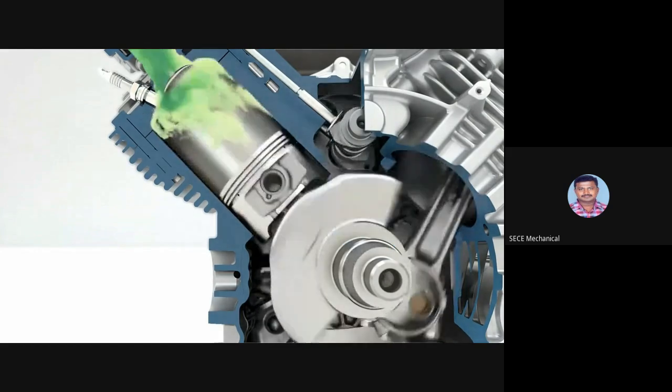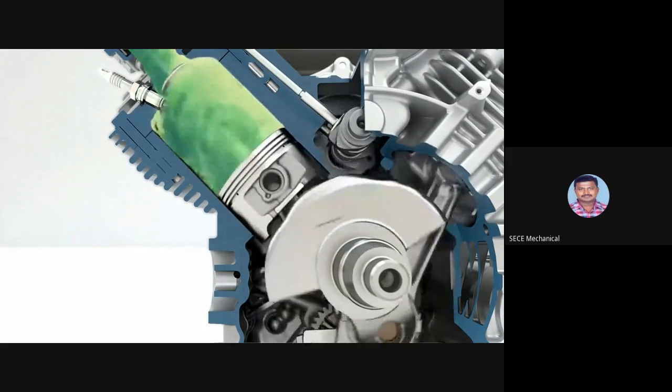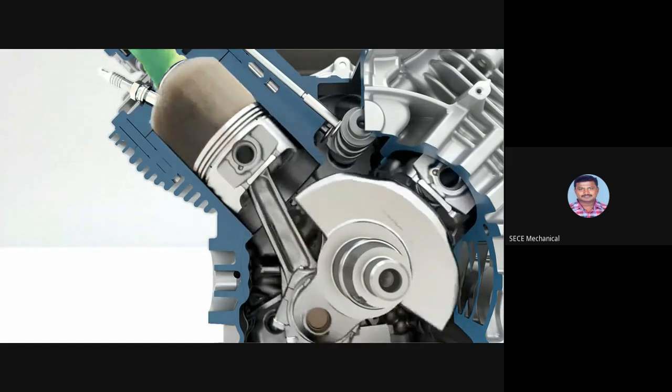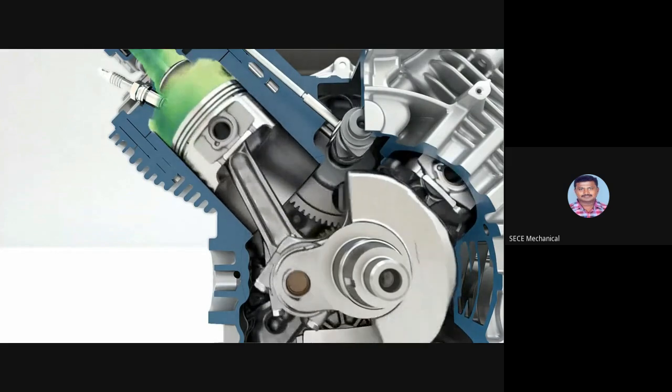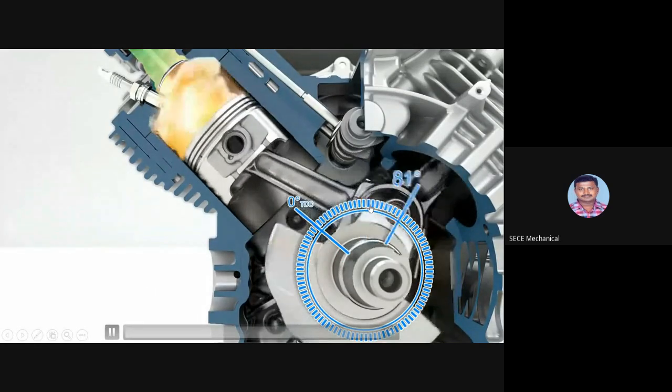If we take a closer look at the process, fuel takes some time to burn inside the combustion chamber relative to engine speed. To accommodate this, the spark event needs to happen much earlier than the piston achieving top dead center. Here we can see the fuel-air charge being compressed during the compression stroke. Once the crankshaft reaches a predetermined angle, as pointed out to the ECM by the crankshaft position sensor, the ECM closes the ground to the ignition coil, completing a circuit. Up to 15,000 volts now travel at the speed of light to the spark plug and jump across the air gap to start the fire in the combustion chamber.